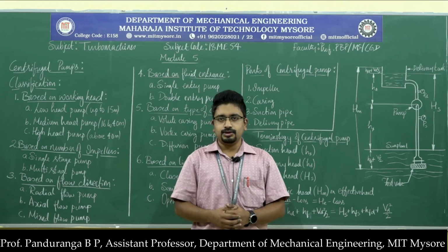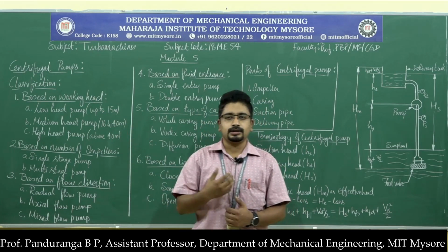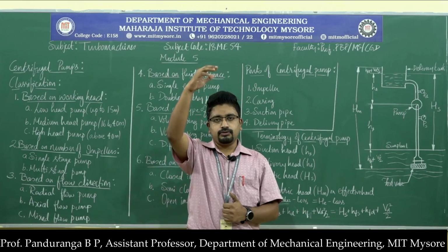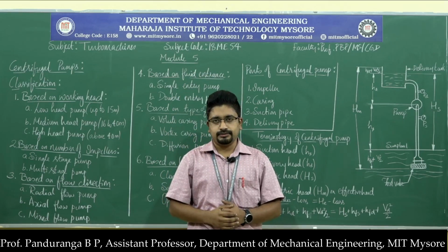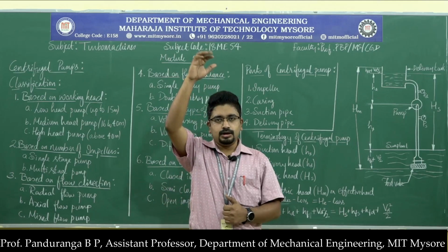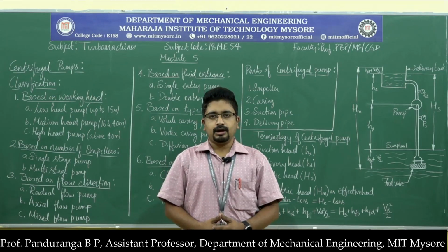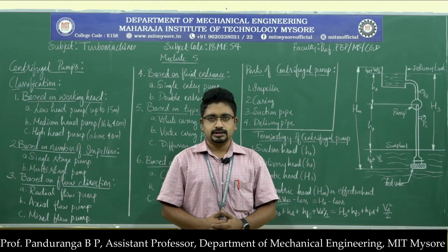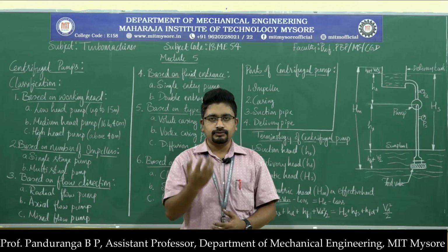But here what we are doing is converting the mechanical energy of the impeller or the runner into fluid power. We are going to store the water or other fluids at a higher energy level, maybe at a higher position, at a higher height, or maybe in the form of compressed air. When we are dealing with a power absorbing turbo machine, we are converting the mechanical energy of the impeller into kinetic energy or fluid power.